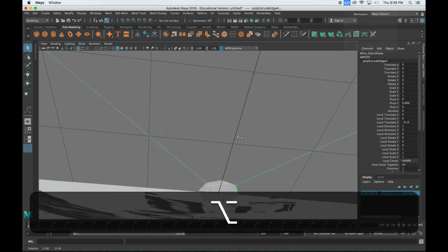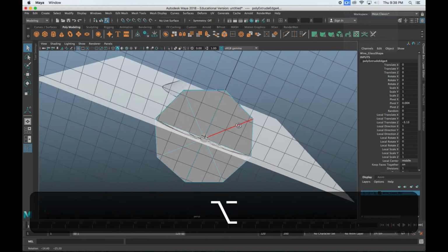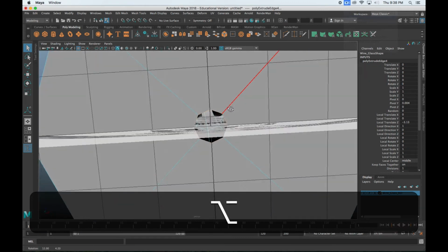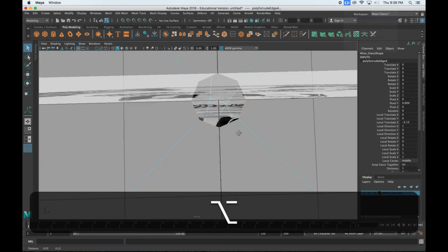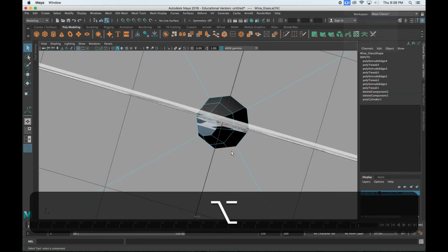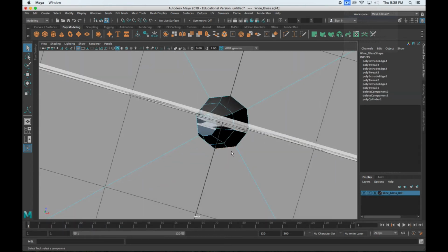Okay, so what I want to do here, and this is a new thing that I haven't really covered yet, is I want to fill this hole in so that it's a solid piece. And the way that I'm going to do that is I'm going to select, and I need to do this so that I'm left with all 4-sided faces. And this is one of the reasons why I choose 8 or 12 subdivisions, because they just fill in very nicely. Choosing prime numbers gets really tricky with this, so don't choose things like 13 and 17.